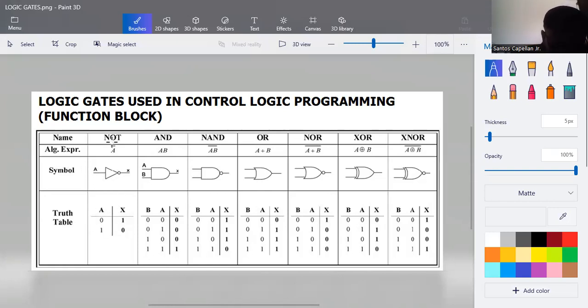That's why here we have a NOT gate. So this is digital, okay? So we have an input 0, then let's say the input here is 0, then the output will be 1. Why? Because we are negating or inverting the input. So if you input a 0, then the invert of that signal will be 1. So that is the function of this small circle.